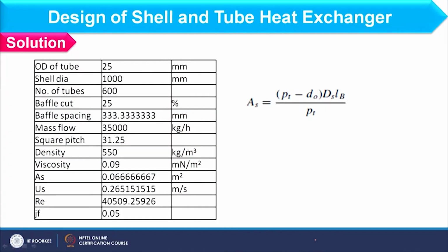So, when you consider the pressure drop in the cross flow zone, you have to find out delta Pi, and delta Pi is basically the pressure drop in the ideal tube bank, right. Now, if you recall the expression of delta Pi, it consists of NCV, US and other parameters. So, we have to find out US, that is the shell side velocity at bundle equator, and that will depend on the AS value, right. So, let us start the solution of this problem.